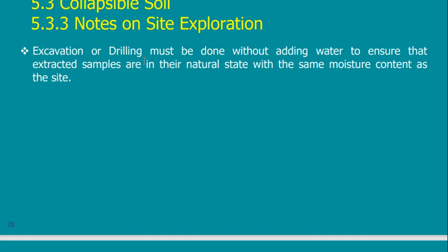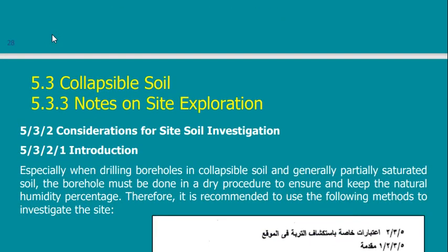This soil is affected by water. If it is affected by water during site investigation, then the sample will be already affected by water, and once it reaches the lab, they will not know that there was some kind of cementation in this material. They will not know, because you have already sent a sample after losing the cementation of this soil.